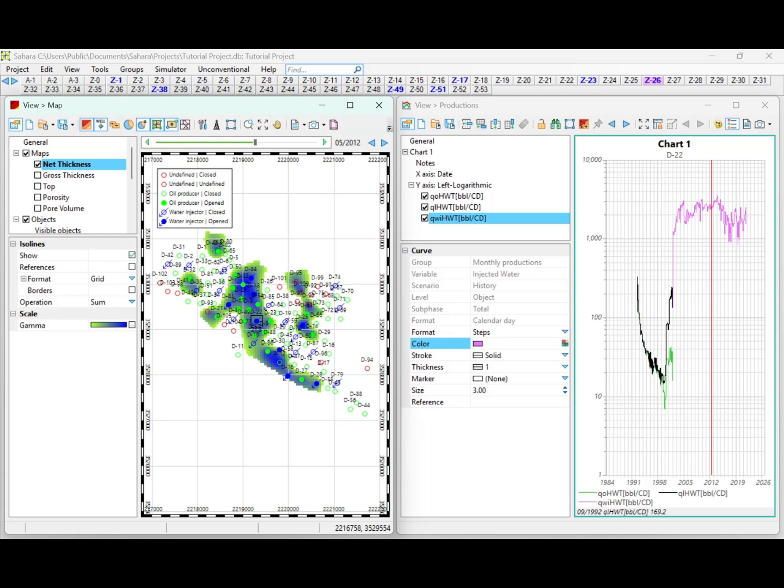But take into consideration that you will need to have an idea of what the water saturation is at the start of the secondary recovery. Also, if you have gas saturation at the beginning of the secondary recovery, that is important as well. You have to consider that. Understand your residual oil saturation. Have as well your connate water saturation, which is the initial water saturation of the project. Which are all the initial saturations. Those are important as well, because we will need them to do some of the calculations for the initial water saturation at the secondary recovery.